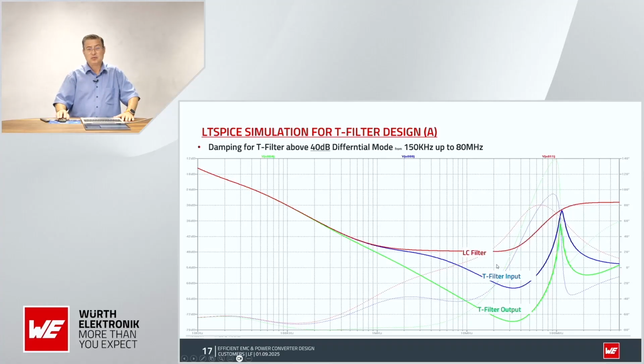You will need a T filter. For this reason we decided to use a good T filter for the input and another T filter for the output, because I'm afraid the output will be noisier by boosting and the input less noisy, and that's why the input filter is a little less efficient than the output filter. They are not 100% the same, both because of the switching frequency.